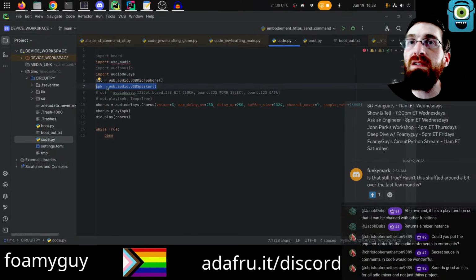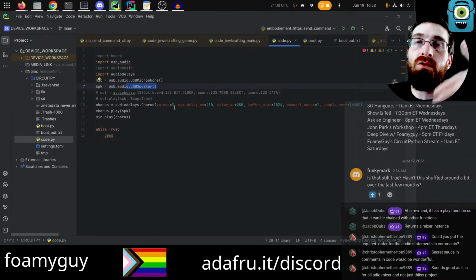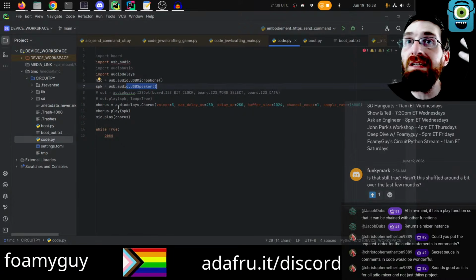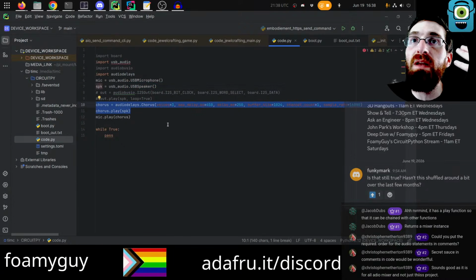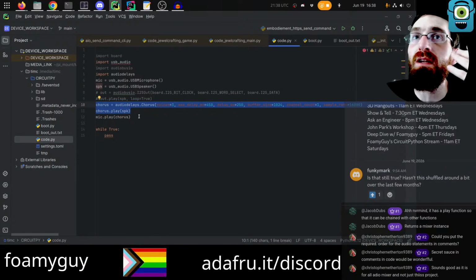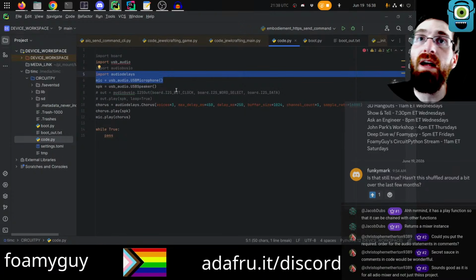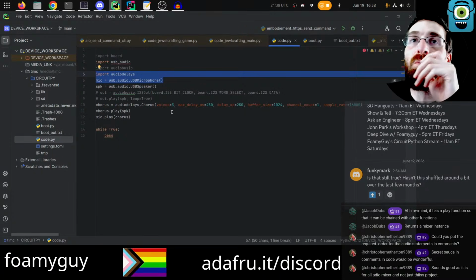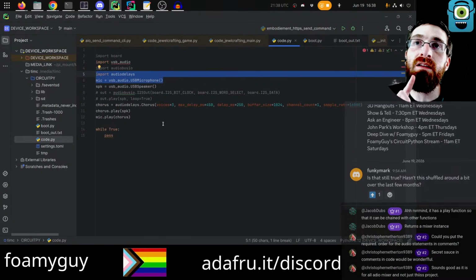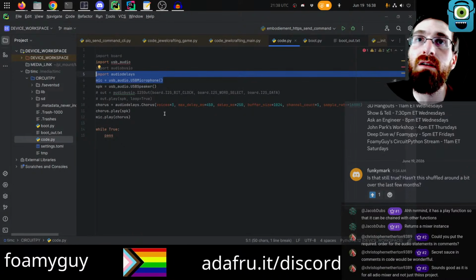So the PC is going to send sound to the microcontroller as though it was a speaker. We can get that sound, manipulate it using the effects chains, and then play it back out the USB as though it was the microphone back into the PC. So the PC can send some audio out to us and then get back some modified audio on the microphone channel.